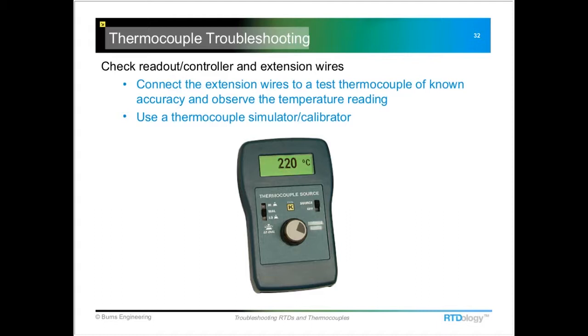That would be the first thing that I would look at. And there it could be a simple test of just adding some insulation around the probe. And if it's in a piping system, for example, maybe a little insulation around the pipe on either side of where the measurement point is being taken, just to take that stem conduction potential cause off the table.